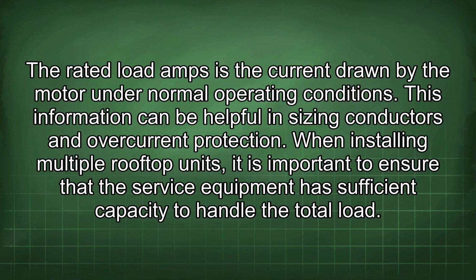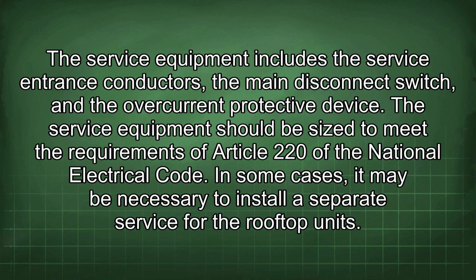When installing multiple rooftop units, it is important to ensure that the service equipment has sufficient capacity to handle the total load. The service equipment includes the service entrance conductors, the main disconnect switch, and the overcurrent protective device. The service equipment should be sized to meet the requirements of Article 220 of the National Electrical Code.